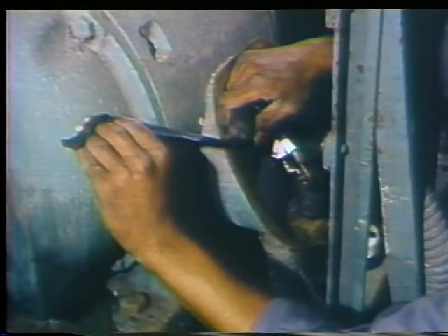Next, reconnect the power leads. Check the lead markings and reconnect them in their proper order. Then wrap the leads with insulation tape. Insulation tape prevents grounds from occurring and also protects the leads.